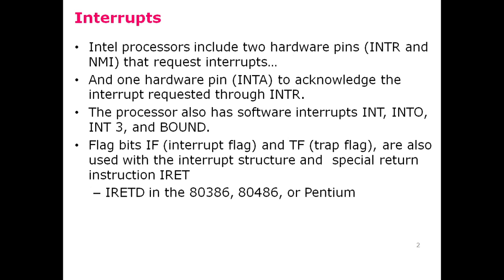Similarly, in the microprocessor, there is one hardware pin called INTA, that stands for interrupt acknowledgement. That acknowledges the interrupt request through the interrupt request pin. So whenever the microprocessor receives an interrupt through the interrupt request pin, that interrupt is acknowledged through this INTA pin, which is an output pin.